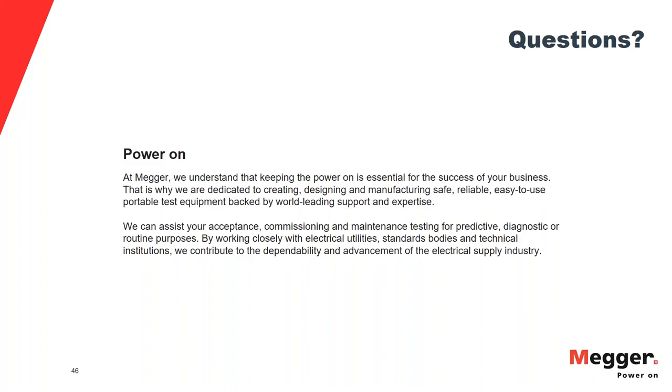All right, next question. Does the fault current always lag voltage? If so, why? Mohit, can you take that one? Yes, I can take that one. It is not necessary that the fault current will lag the voltage. When you have high capacitance on your transmission line, meaning that the capacitive reactance is higher than the inductive reactance, you can have fault current leading the voltage. So there are some cases where you can also have faults where the current is leading the voltage.